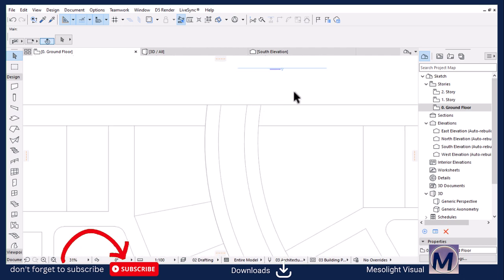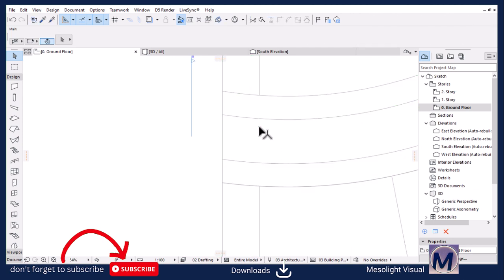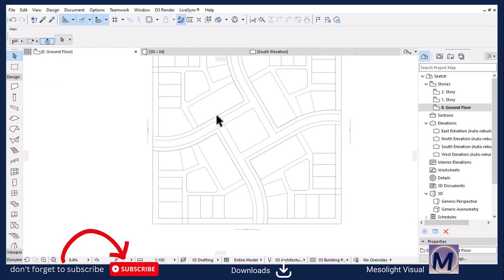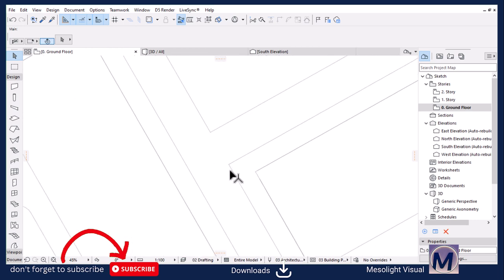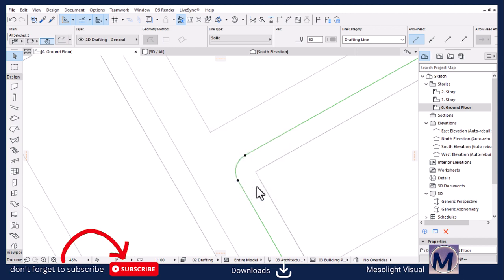Move to the other side. Here it's fine. This side needs a bit of work as well. Let's just do that, and then go down here. Make sure you do the same as well. Perfect. So now I think everything is super. Now we need to round the edges off, because it's a road, it cannot be 90 degrees. We're going to use the fillet tool to fillet with a radius of 3.5, as you can see.